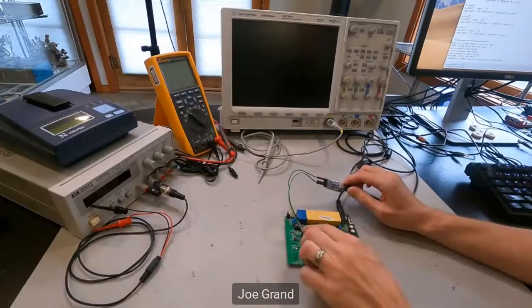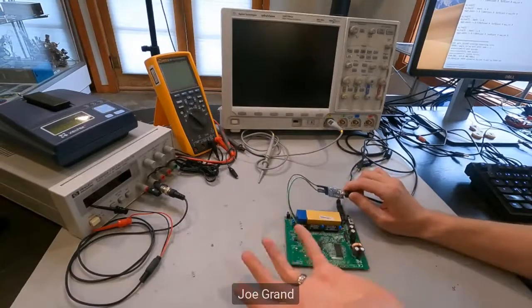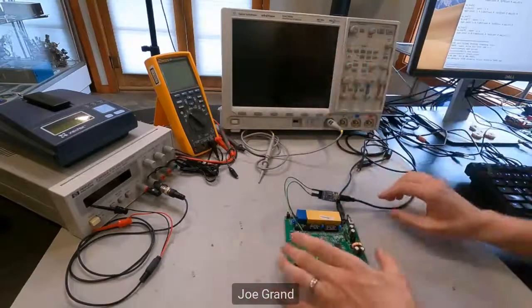If you don't know, though, if you identify ground and you identify one of them you realize is the system voltage by following where it goes, then you just try one orientation of the other pins. If it doesn't work, you just flip them around. If you don't have a scope to probe around first.